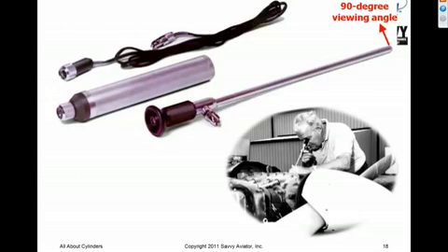We'll talk a little bit about borescopes. This is a rigid optical borescope. It happens to be the borescope that was called out in Continental SBO 3-3, which is their service bulletin about how to do compression tests. Continental requires that a borescope inspection be done every time a compression test is done. And at the time SBO 3-3 came out, which was in 2003, this kind of borescope here was the state of the art. It has an eyepiece, it has a light source, it has a little 45-degree prism at the end of the probe, so that when you're looking through it, you're looking at a 90-degree viewing angle. In other words, you're not looking straight out the end of the probe, you're looking 90 degrees to the probe.